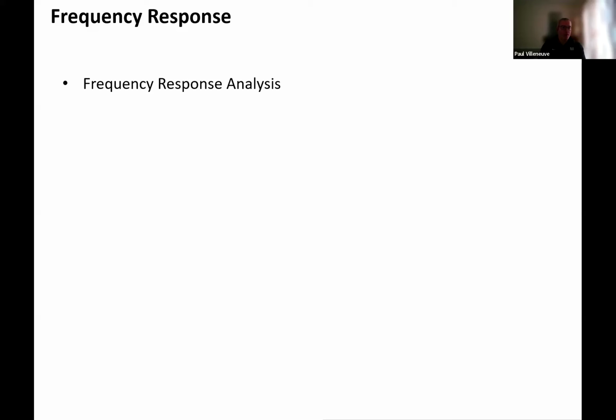It's not one that I've frequently seen in control systems analysis. There are some systems that have sinusoidal inputs. One of the things I can think of is if you're on a diesel generator, and one of the things that's really important to know is the speed of operation. And one of the things that they do is they have almost like a proximity sensor, but it uses magnetics. And so as the teeth on the sprocket go by, it creates a little pulse because the sprocket's made of some sort of ferrous material.